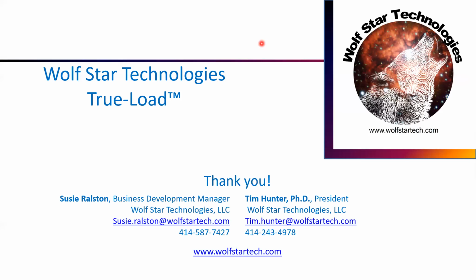We'll have FEA on the front end to help us place strain gauges on the structure, understand where the strain gauges need to go. But then once we've laid the strain gauges, we can take the correlation matrix that we extract from the FEA model and burn that onto a chip, and then we can set up real-time load monitoring and damage monitoring on your structure.